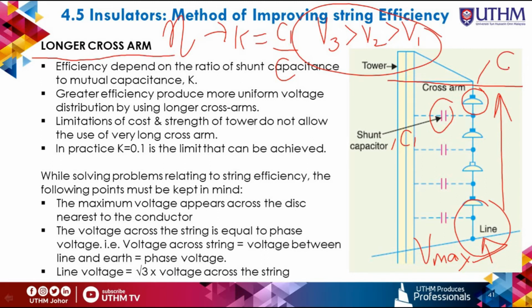The string efficiency depends on K. The lesser the value of K, the greater is the string efficiency, and more uniform is the voltage distribution.